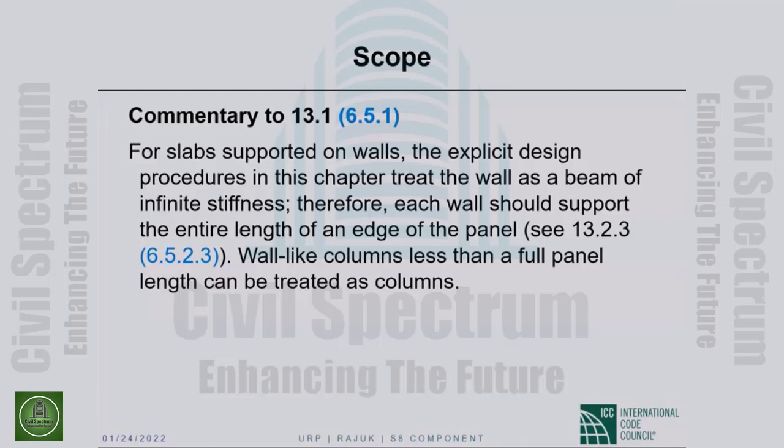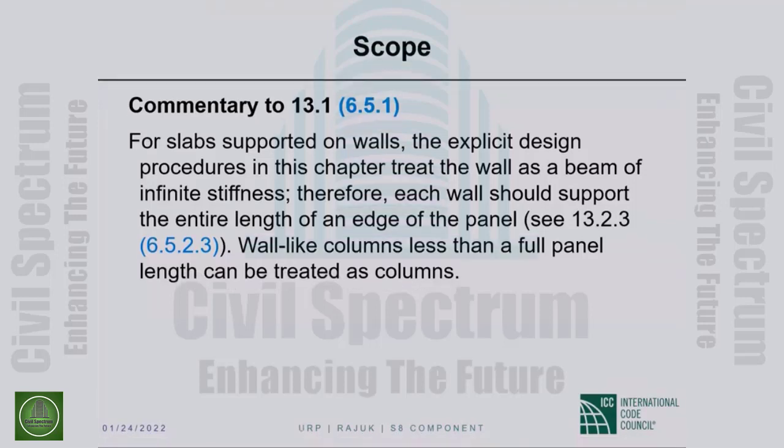Wall-like columns, long columns, less than a full panel length, can be treated as columns. So if the full panel length is not supported, then a wall-like column is treated as a column, not a wall.